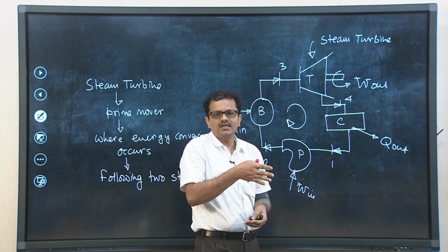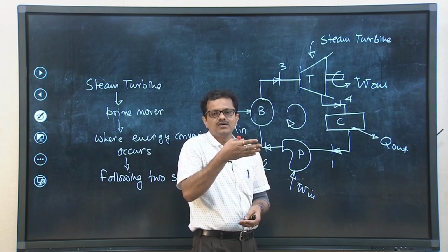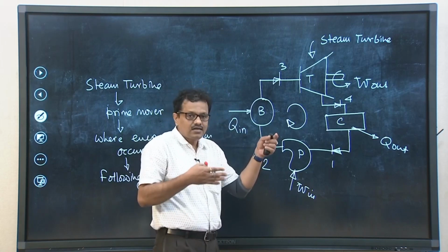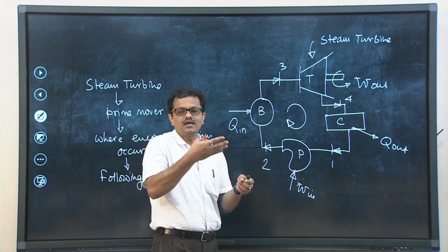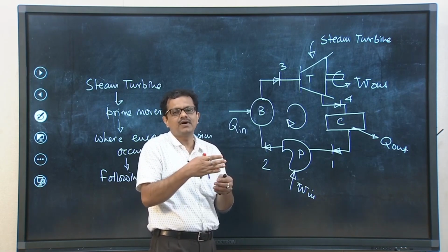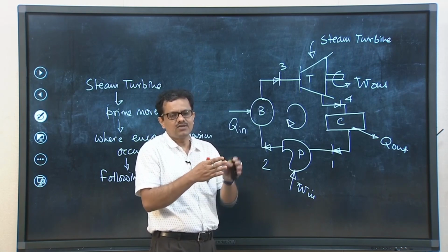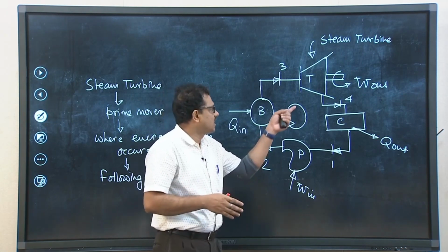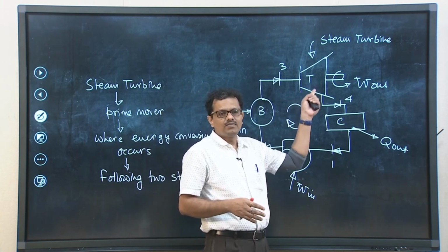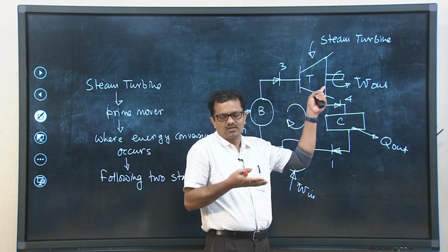So, before it leaves the nozzle and strikes the turbine blades, the kinetic energy of the steam jet should be very high. When the steam jet strikes the turbine blade, there will be some deflection, which is decided by the blade angle, and at the cost of that momentum change, a loss of momentum will occur, and that momentum will be absorbed by the wheel, producing a torque.